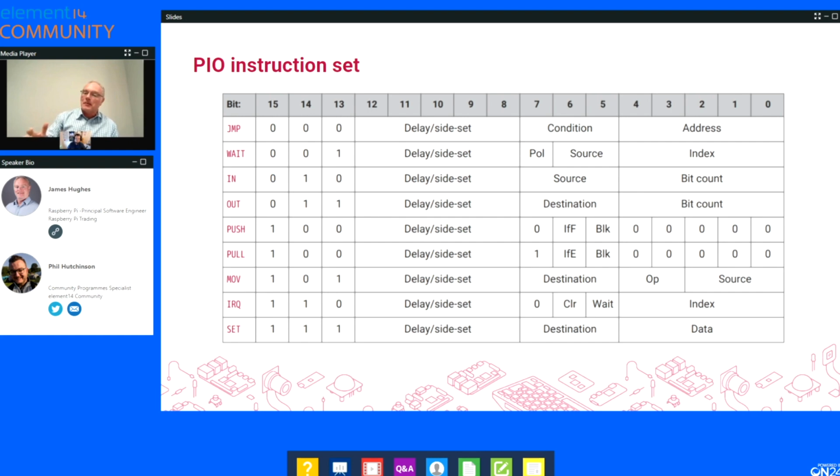This is just because it's such a common operation, we put in a special bit of hardware in the PIO that means that when it gets to a certain point, if a buffer becomes semi-empty, nearly empty, it can be automatically filled up by the hardware, so you don't actually have to write certain instructions, which is useful because each PIO block only has 32 instructions, and you have to spread that over all the state machines in that PIO.